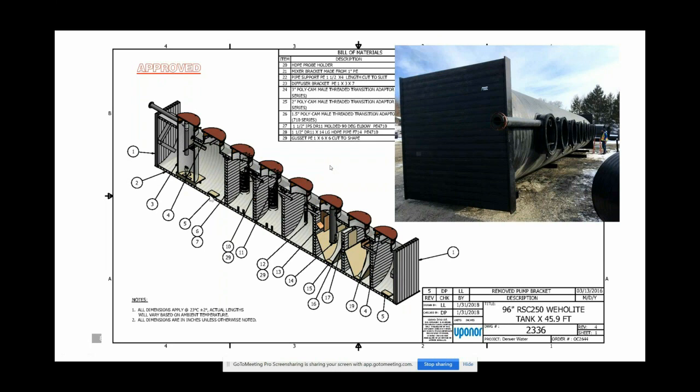And within these tanks, you'll see small platforms for pumps. We're not providing the pumps for this system, but we did incorporate these platforms. The pumps would be removed using lifting chains instead of guide rails here, so you won't see any guide rails. These pieces in the bottom of the MBBR chambers are for diffusers.